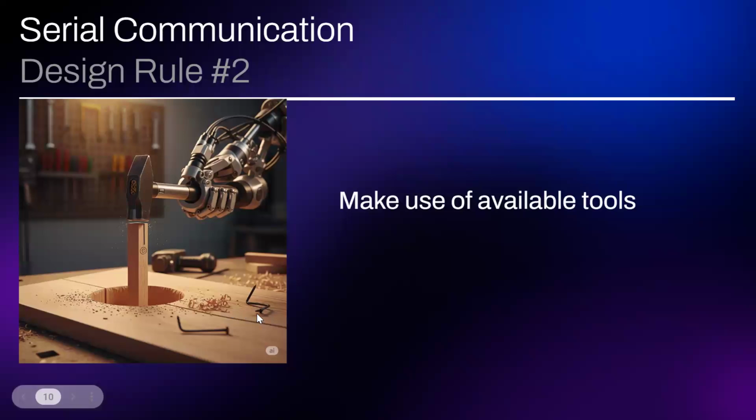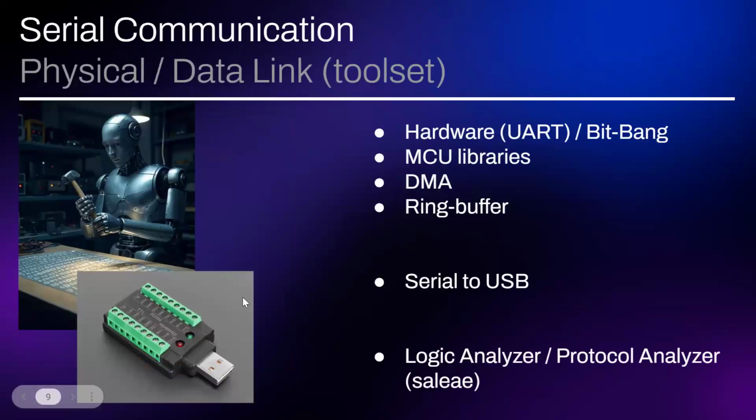What it says is logic analyzer or protocol analyzer. What those are is they're fancy oscilloscopes. They watch the ones and zeros coming in, but they can interpret those ones and zeros in terms of whatever protocol you're using across there.